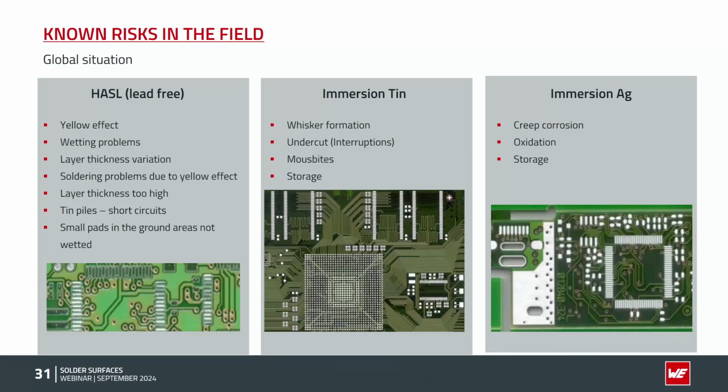Immersion tin: from immersion tin we all have heard about whisker formation, which comes from the mechanical stress inside the grains of the tin. So without any current or voltage from outside, that could happen even in the storage area.